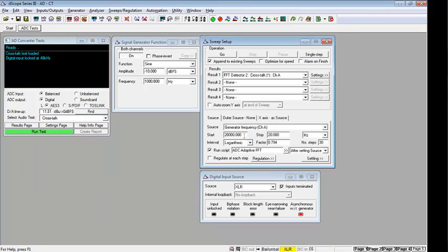So once again, I'm running a sweep from 20 kilohertz to 20 hertz, again using this adaptive FFT size script here that will look at the crosstalk amplitude, look at the crosstalk frequency, and determine the most appropriate FFT size to avoid wasting time when we can get away with low resolution, but taking care to ensure that we have high resolution when we need it.